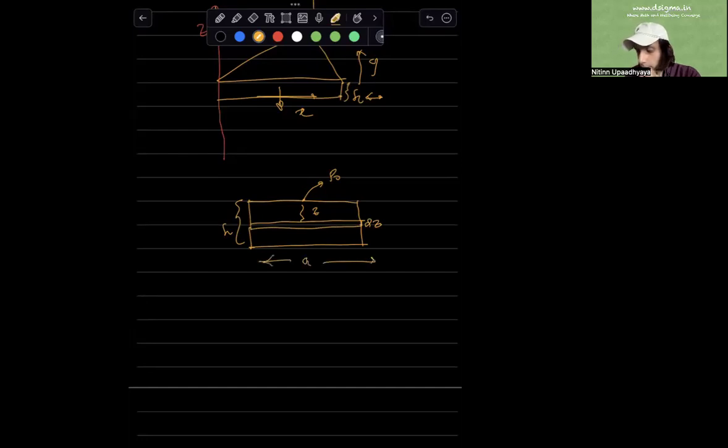and the side of this triangle has a length a. Then the net force acting on this element by the pressure being exerted by the fluid column would be given by force is pressure times the area of this element. Now the pressure at this depth is approximately P naught plus rho g z.